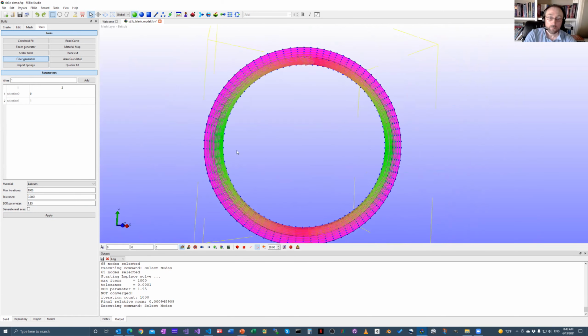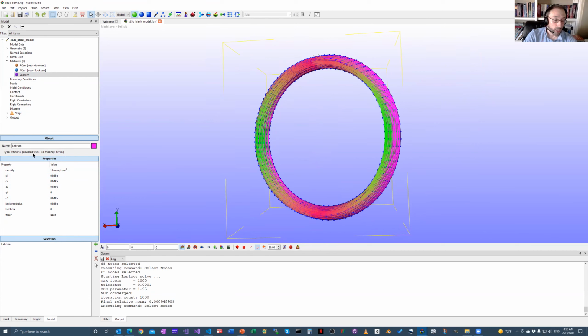So this is, by the way, a combination of a Mooney-Rivlin matrix and then a fiber contribution. The Mooney-Rivlin parameters are C1 and C2, and we'll just set C1 to 10 and C2 to 0. And then for the fiber components, which are C3, C4, and C5, we'll just set these to 1. For the bulk modulus, we'll choose 100. And then for the lambda, we'll choose 10.